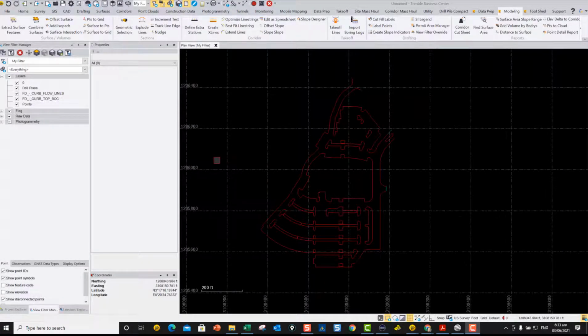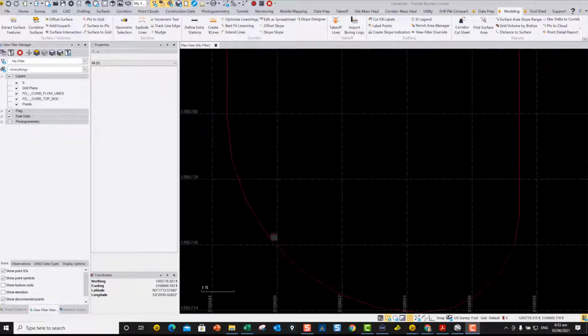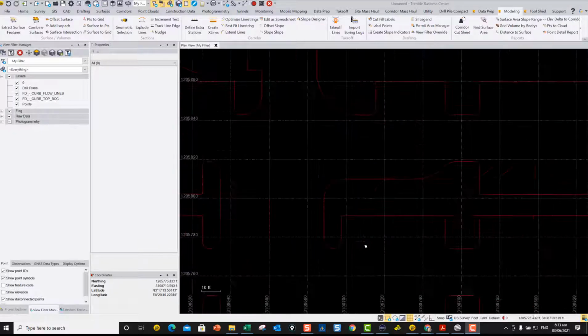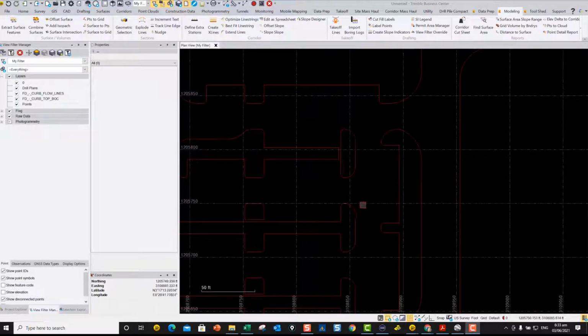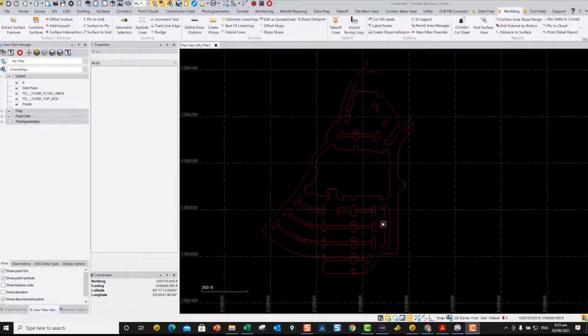Today I'm going to talk about the new commands that we introduced recently for slipform paving calculations. In this example I've got a parking lot, and if we take a look at the parking lot islands, you'll see that the curves are not actually curves, they're chorded lines. The data here isn't optimized at all for slipform pavers, so we're going to do some work on this data to make it useful for slipform paving operations for curb and gutter machines.